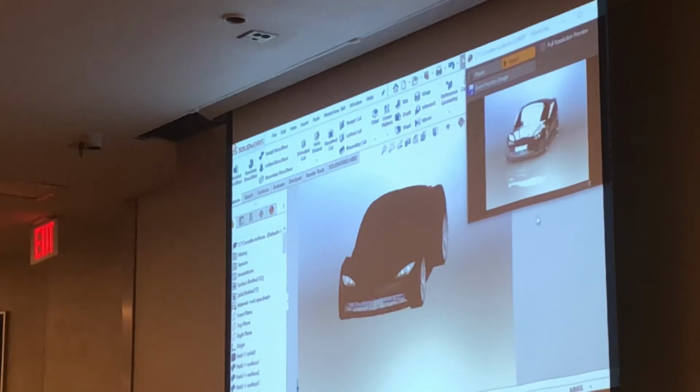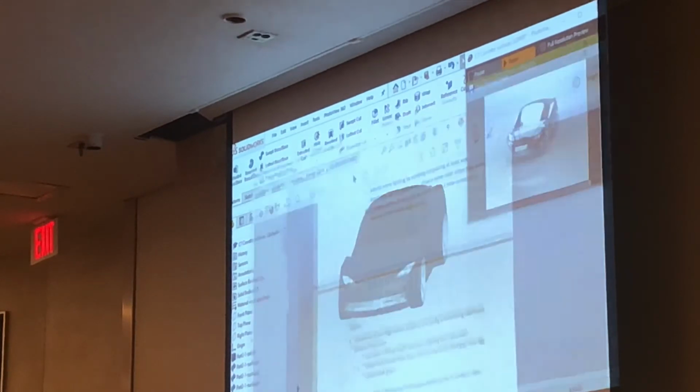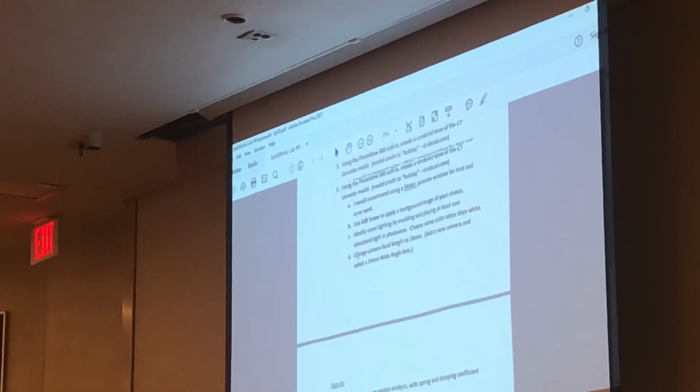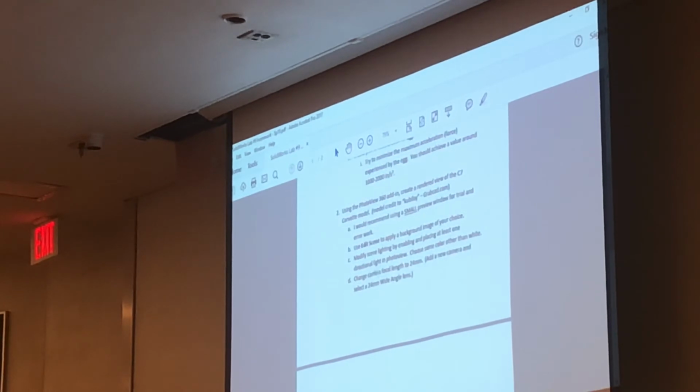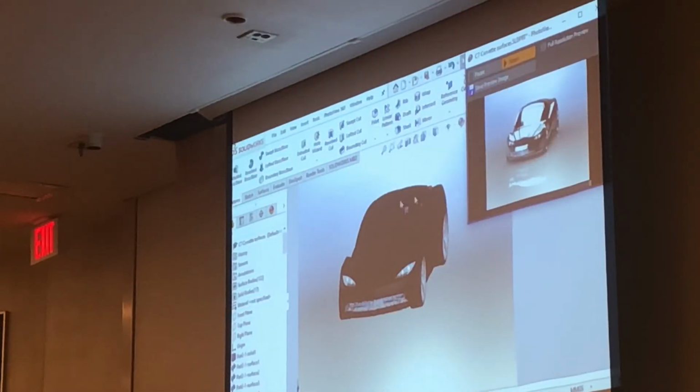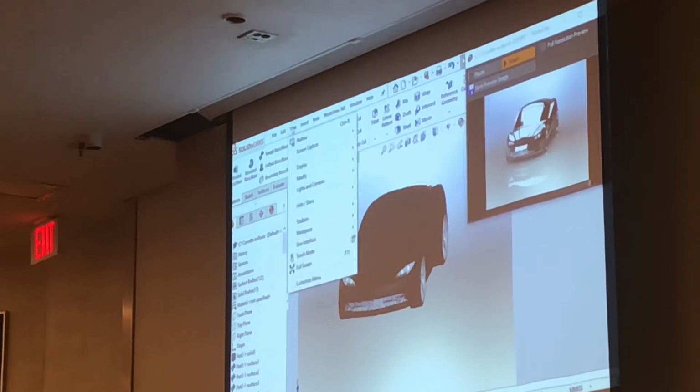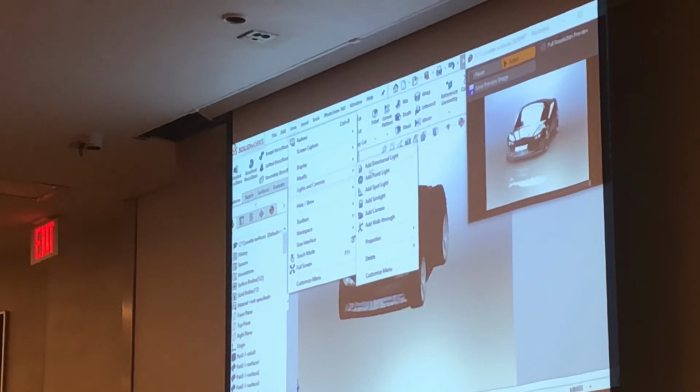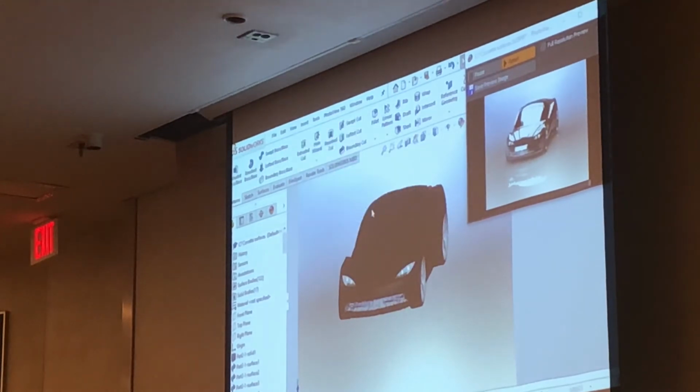Yeah, I asked you to produce an image. I said to change the camera focal length to 24 millimeters, which means define a camera lens that's a 24 millimeter wide angle lens. So the way we do that is in our menus, we go to the View menu, and we go to Lights and Cameras, and we say Add Camera.